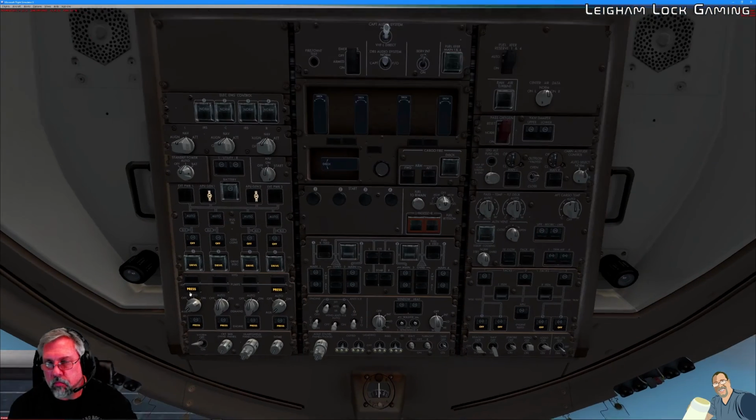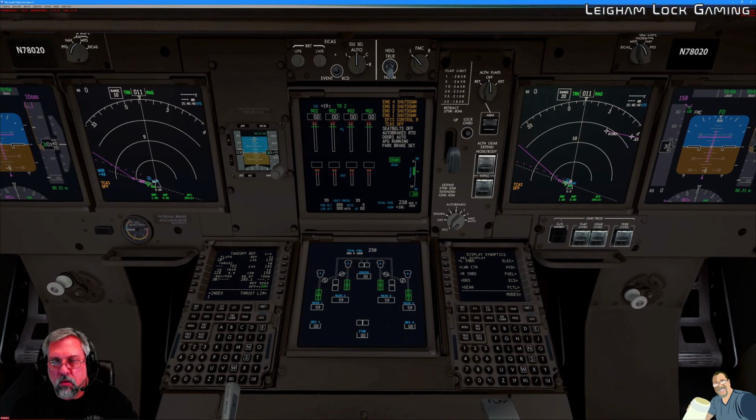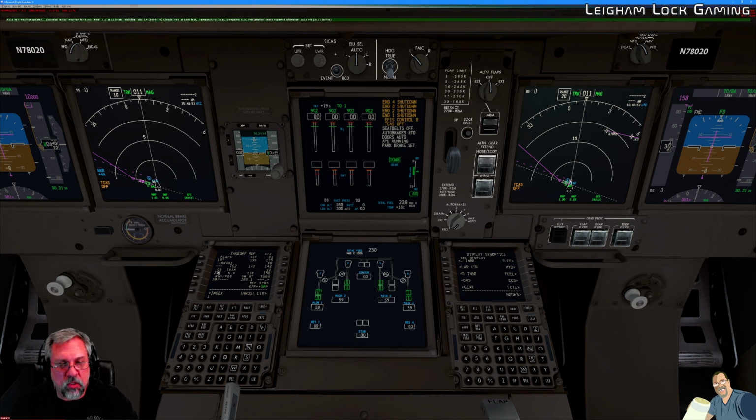Alright, we're getting ready to start the engines up here momentarily. We're going to put our beacon light on, both the top beacon and the lower beacon should be on, that's both. We want to set our stabilizer trim. The stabilizer trim reference is right up here on the main ECAS page. You can see it's set currently for 6 right now. And our trim, based off of the information put into the aircraft and our payload, should be 5.9. So we can adjust that from our control stick, 5.9.